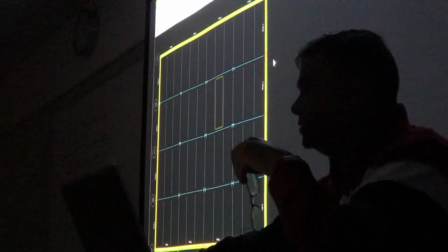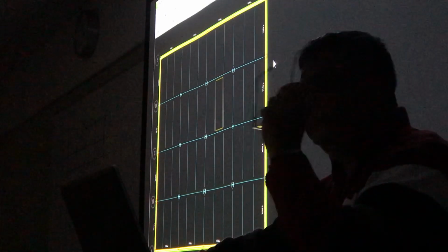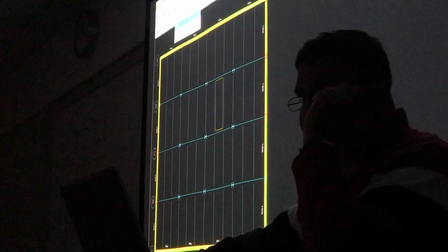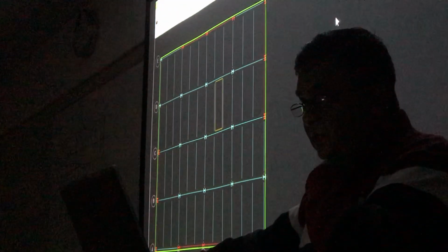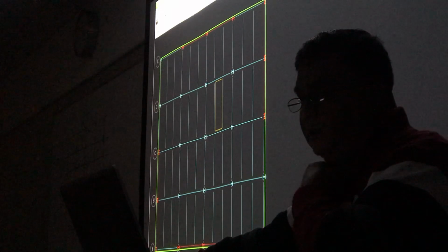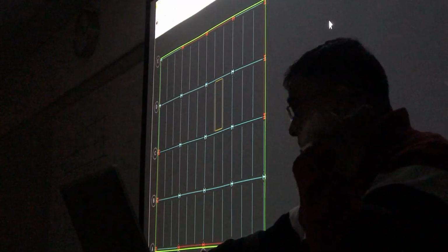And as I said, I will copy them for the first floor as well as on the roof. So how do I go? Go here, first floor doesn't have anything. So go layout, type, copy, and copy everything from the typical floor. Done? Okay. Also go to the roof level and layout, type, copy everything from the typical floor. Okay, done.